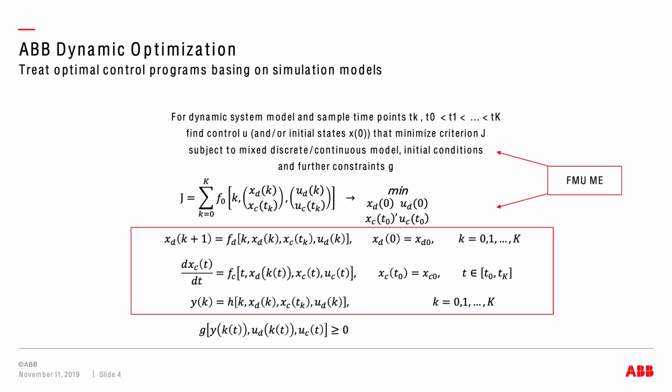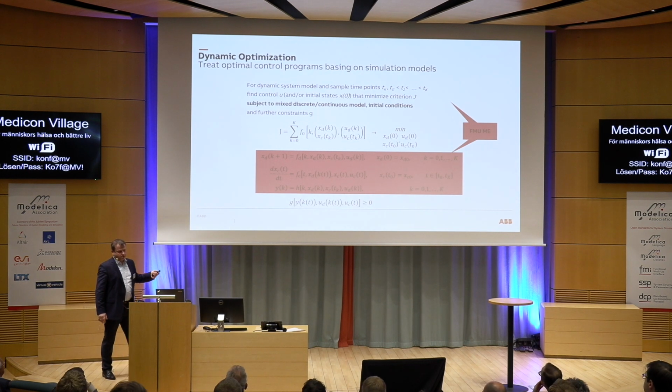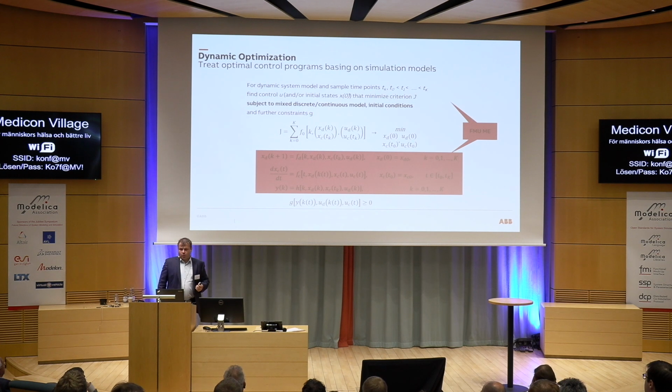which oftentimes is linear or quadratic weights on model variables, on some dedicated model outputs, but the sophisticated equations are formulated inside the model. And we add constraints, which again mostly are lower and upper bounds, either hard constraints or soft constraints on model variables that we have in the FMU. And based on that model, we solve, then I come back to this later, to newer developments. This we solve on machines which scale from small IPCs to big cloud installations and multi-core machines.